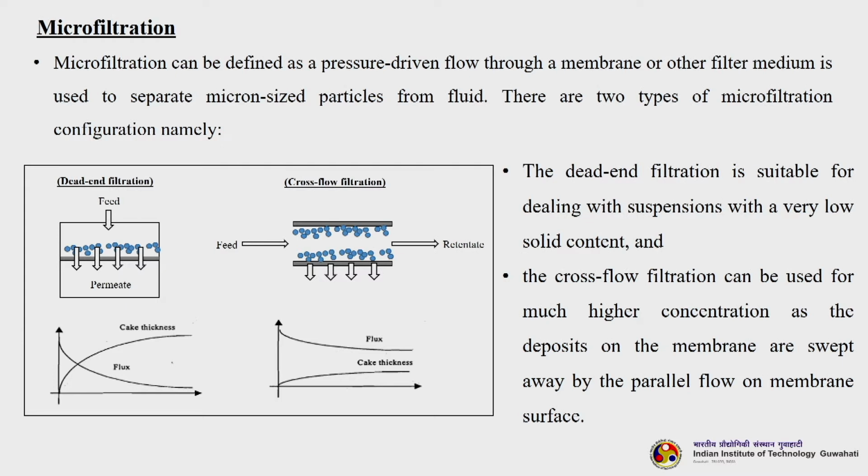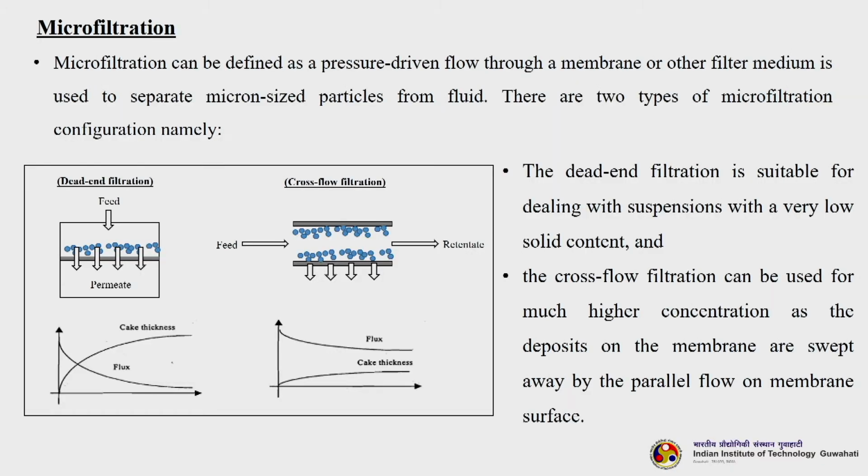Please note that the dead end filtration is not a commercialized industrial application. This is used only at laboratory scale to characterize certain membranes and to develop a process. There are no industrial applications of that, and the major application is of course the cross flow filtration. It is used for higher concentration as the deposits on the membrane are swept away by the parallel flow on the membrane surface.